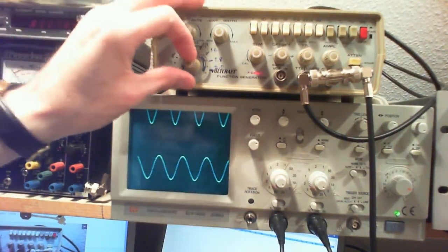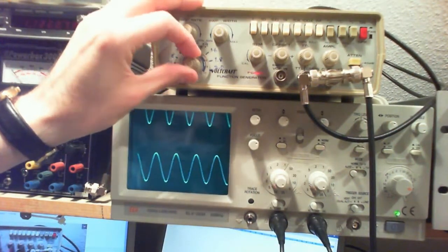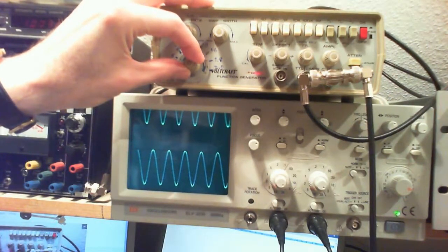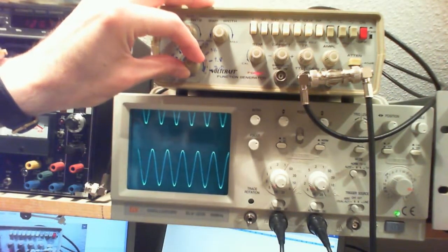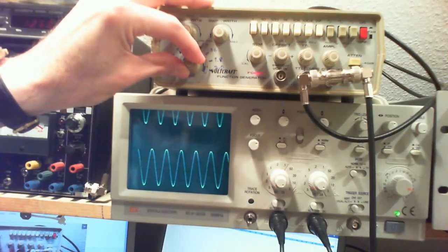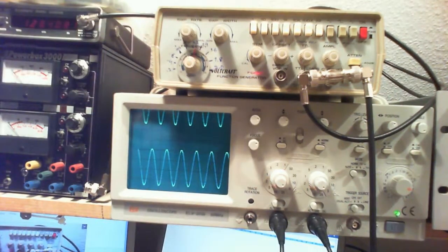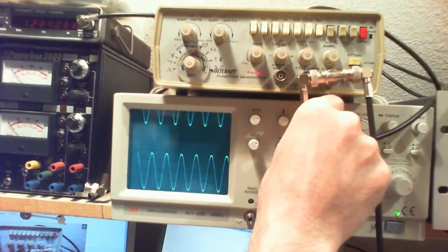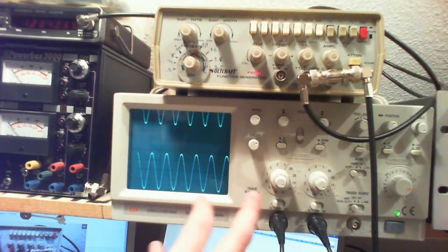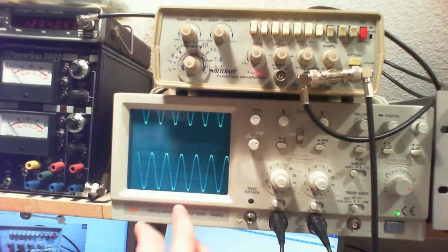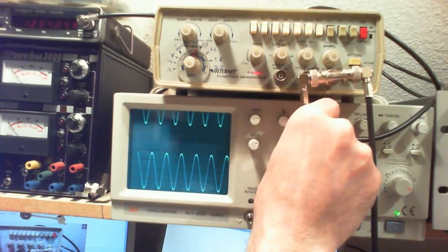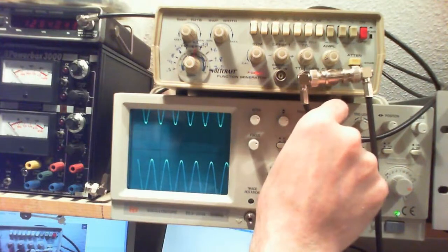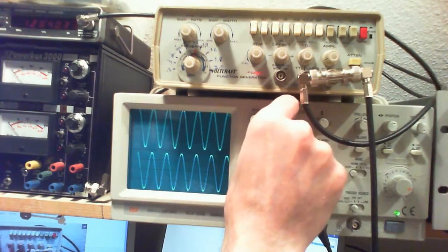Okay, and then if I go all the way up, you see over here what happens as I increase the frequency. I get all the way up to about 1.3 megahertz or so, and my output here is at about the same as the input. So 3.8, and the input is basically the same thing.